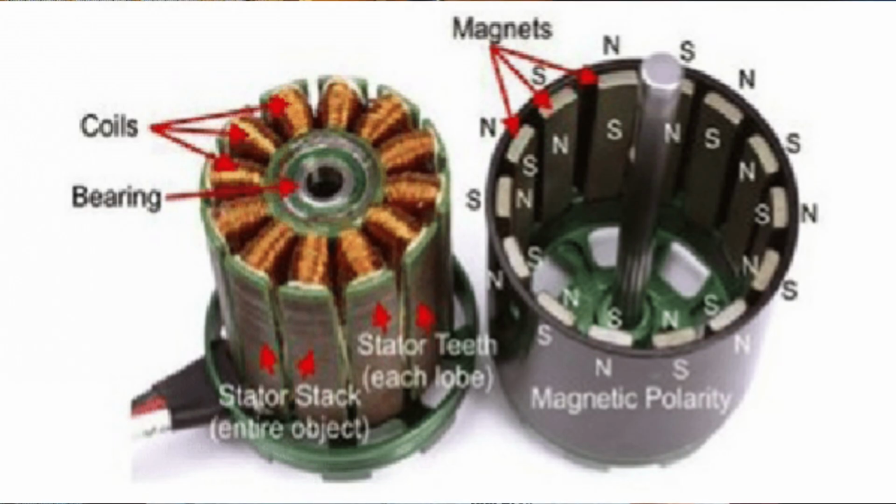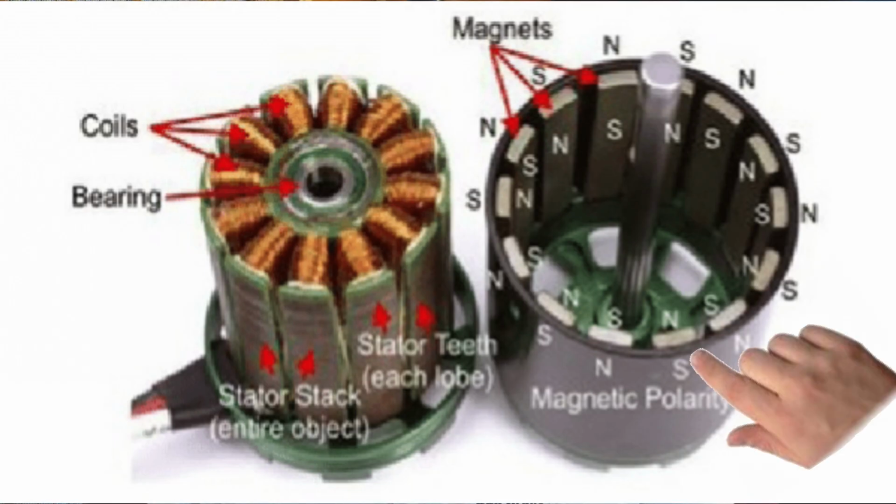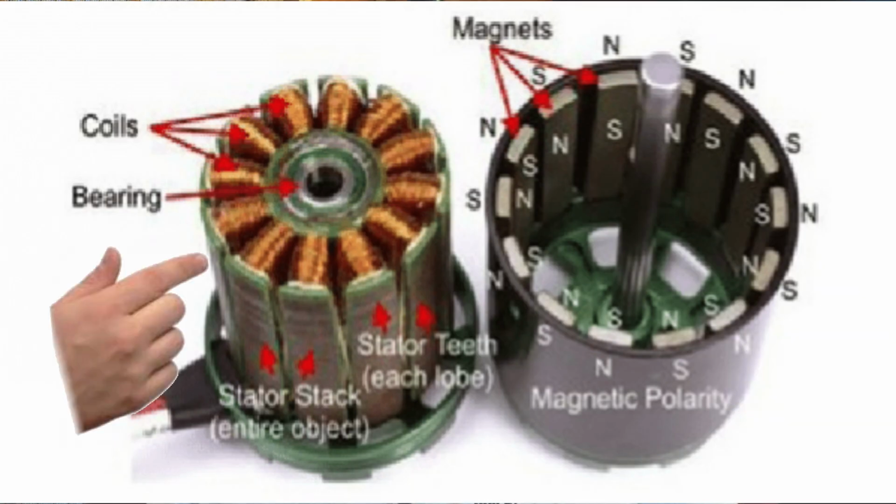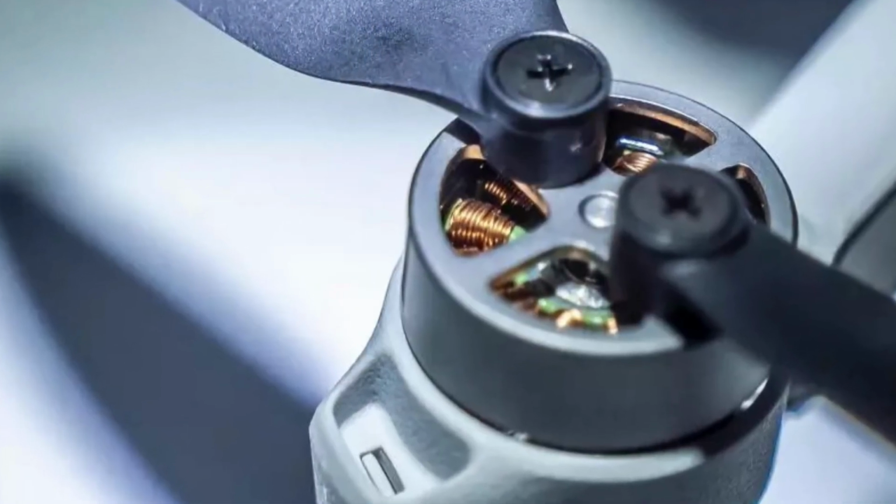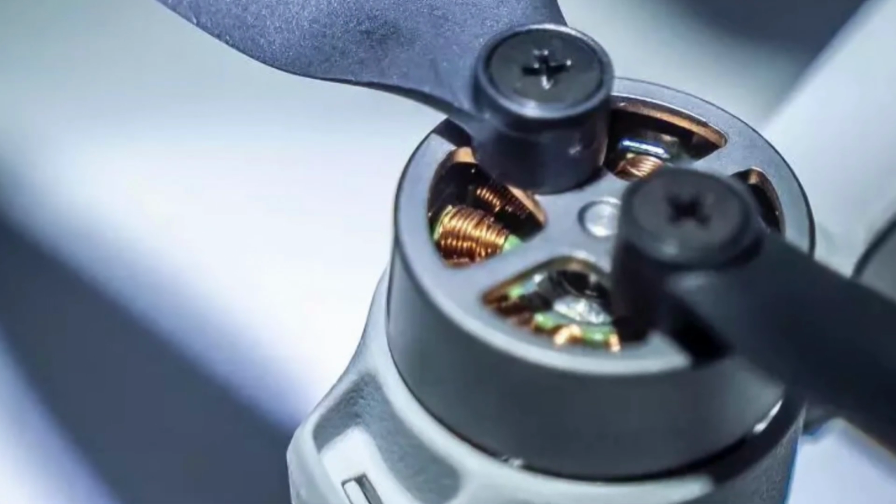In an outrunner design, the outer part of the motor rotates, and it is the inner stator unit that is fixed. And since the stator isn't rotating, it doesn't need those nasty friction-generating brushes. Hence, brushless. Although brushless motors tend to be more expensive, they're way more efficient and better performing than brushed motors. They also tend to be quite exposed, so be sure to keep dirt and grime out of them and especially keep moisture out. Don't fly your drone in the rain or snow.